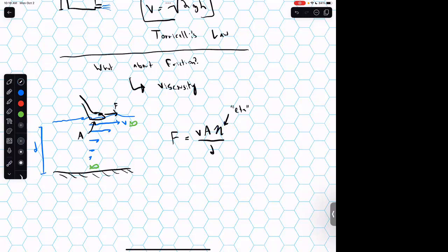So in other words, the deeper the fluid is, the less overall resistance I'm going to feel to the shear I'm applying. And that's due to sort of boundary effects. Okay, so this is the formal definition of viscosity. And I'll just write out what these terms are. So let's say that this is force, this is depth, which is just distance. A is the area, in this case of my hand, and V is just the speed at which I'm shearing. And this relationship implicitly defines viscosity in terms of these properties.